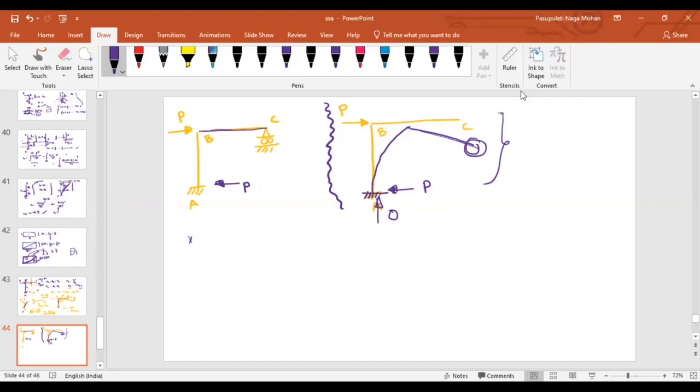If there is no support, the deflection is possible, isn't it? If the deflection is possible, that means as I'm restraining it, definitely the reaction force will develop. If there is no support, this point is going to deflect in the downward direction. But this support is not allowing any deflection. That means obviously the resisting force will develop. Let us say this was the resisting force upward. As there are no other loads, as it is upward, here obviously downward. Some movement will also generate here. How much it generates, we can look into later on.